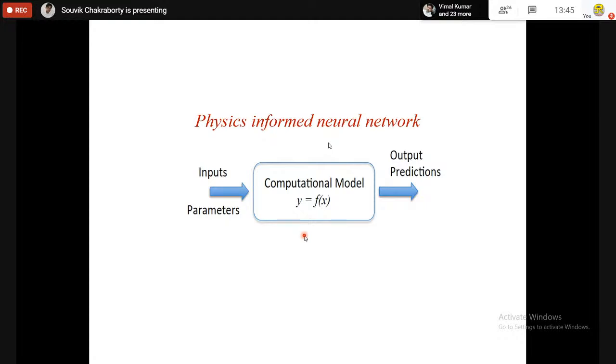But if I go into the basics, you are actually solving a differential equation. Think of a plate. You are solving a plate in Abaqus or ANSYS just by discretizing it. But there is a theory behind that plate. There is a fourth order differential equation that you are solving. Think about even a beam. You know about Timoshenko beam theory, Rayleigh beam theory, and even Euler beam theory and plate theory, obviously. So like that, there are differential equations associated with all the problems that we solve. The only thing is, because you have a software, you don't bother about those equations.